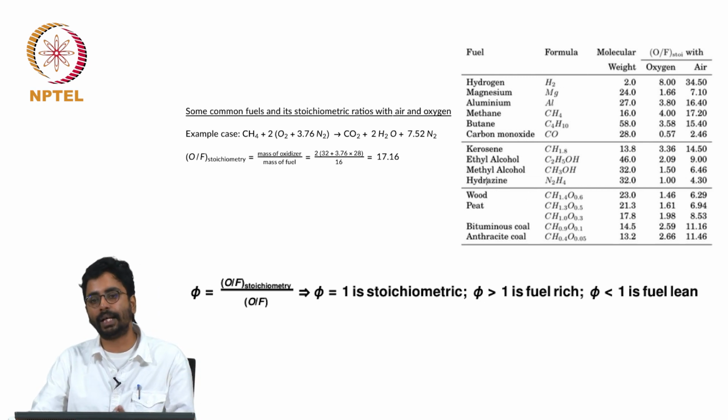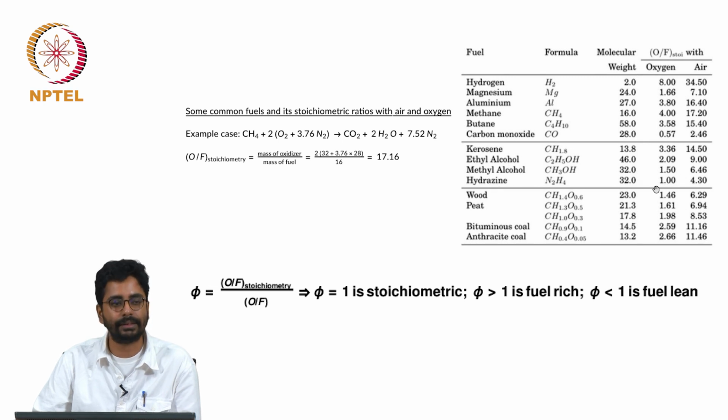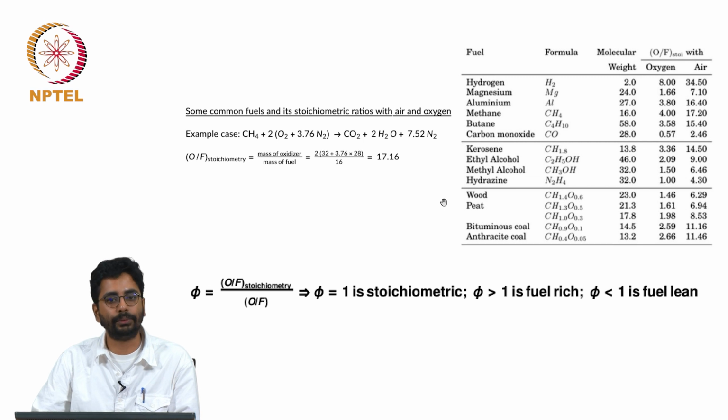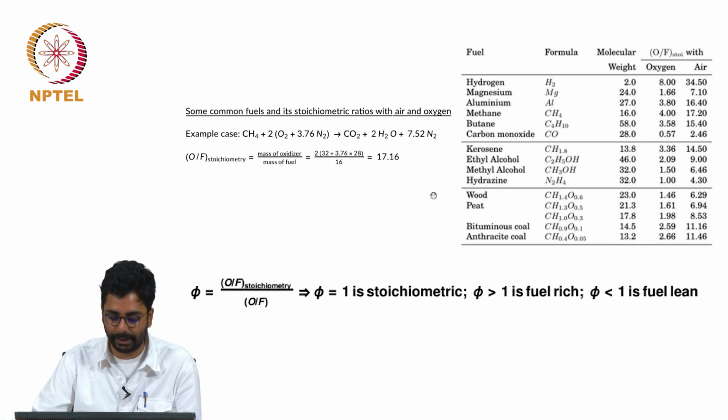In fact, hydrazine can be used both as a monopropellant and as a bipropellant. It can decompose on its own, releasing energy when sprayed onto a catalyst. It can also be oxidized with additional oxygen, because it decomposes into nitrogen, ammonia and hydrogen, which can be further oxidized. There are other interesting fuels also here.